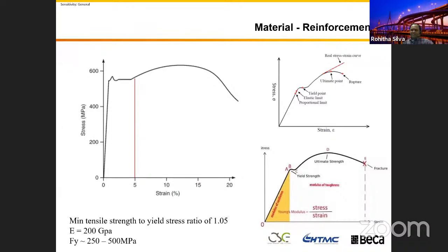design models. Please understand that these more or less try to represent the actual model, but if you really want to design a structure, if you want to check something, now you can use this actual stress strain curve in your structural modeling. For example, most of the software facilitates that. You can input that, but it's not really required that much accuracy when you design a bridge.